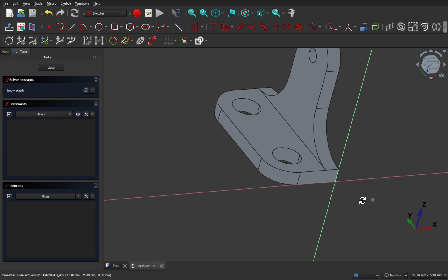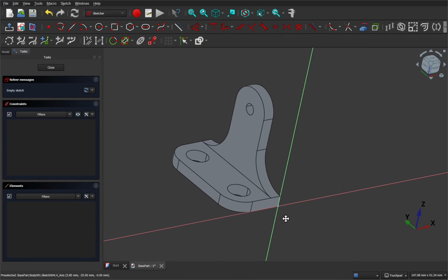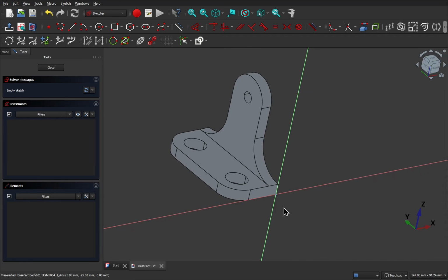At this point, notice how this is attached. The red is the x-axis and the green is the y-axis. But looking at the navigation down here, we can see that the X runs this way and the Y runs this way. So it's actually running this way. And the Z is in place of the Y-axis. So where's the Z gone and why are they orientated in this way that differs to this? Well, the Z with 2D sketches and 2D objects runs normal to sketch. So it'll run perpendicular to the sketching plane. It's running this way.